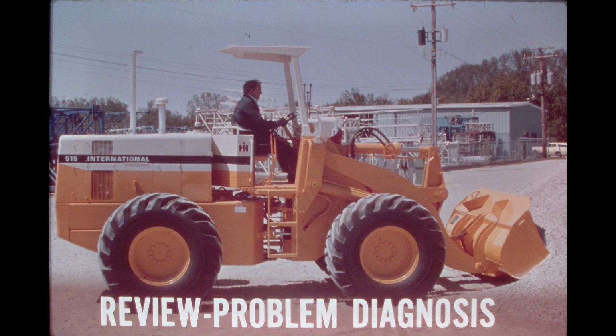The answer to number 3 is B. Main pressure should read a minimum of 310 psi. The answer to number 4 is D. Converter outlet pressure reaches its maximum at all the conditions listed. In each case mentioned, the spring behind the converter regulator spool is at its highest compression.